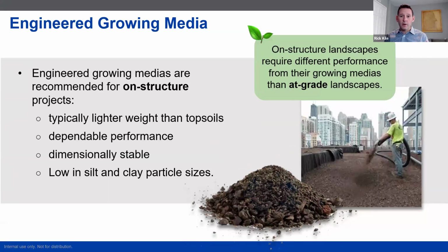There are a number of reasons why we use engineered growing media on the roof. It's typically lighter weight than a comparable topsoil in a given area. Here in Southern California, a sandy loam topsoil, which is most common, weighs about 120 pounds a cubic foot when fully saturated.